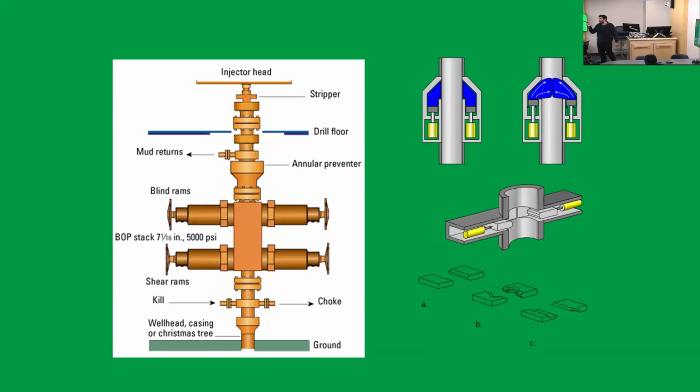That's why a lot of equipment is built for that. The annular preventer is for the annulus. The pipe ram is for the annulus. If it gets into the drill string and is coming up like that, it must be a gas kick as well, because of the density difference. You are in a very bad situation, but it can still be managed.